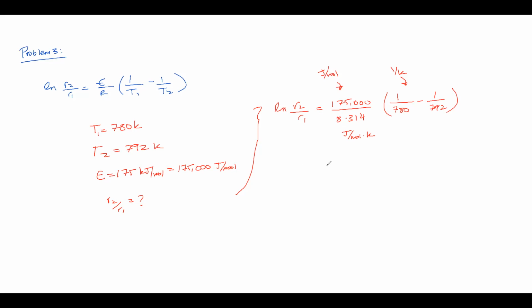And one of the basic things to check if you're on the right track, especially when you're dealing with complex equations, maybe not this one, this is a very basic one, is to check for dimensional consistency, right? If your numbers are dimensionally consistent, then most likely your calculation is correct. So in this case, ln R2 over R1, if you plug in these numbers, you should get 0.4088, and this translates to R2 over R1 being equal to 1.505, right?